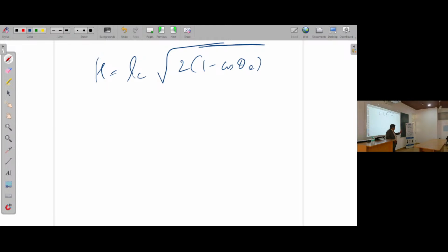So it is basically dependent on the capillary length corrected by some factor corresponding to the contact angle. We don't have to do anything else. It's a very quick way of estimating the height of the film, especially. We use this constantly in various things as a first guess of what the answer could be. So this is one of the elements which I wanted to explain regarding capillary length.